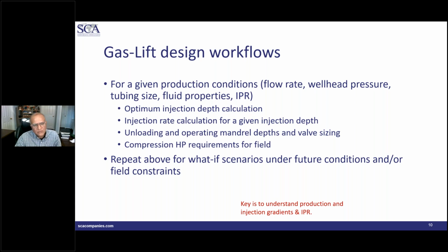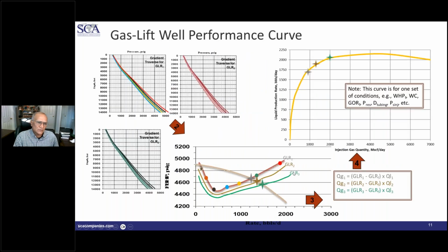And this field constraints becomes more important not only in greenfields, but also in the brownfields. So one thing that helps a lot is if you understand your production, injection gradients, and inflow performance relationship. That should tell you that gas lift is all about understanding the hydraulics. Okay, I'm assuming that you are all familiar with some gas lift. Otherwise, I can spend 5+ minutes just explaining this.